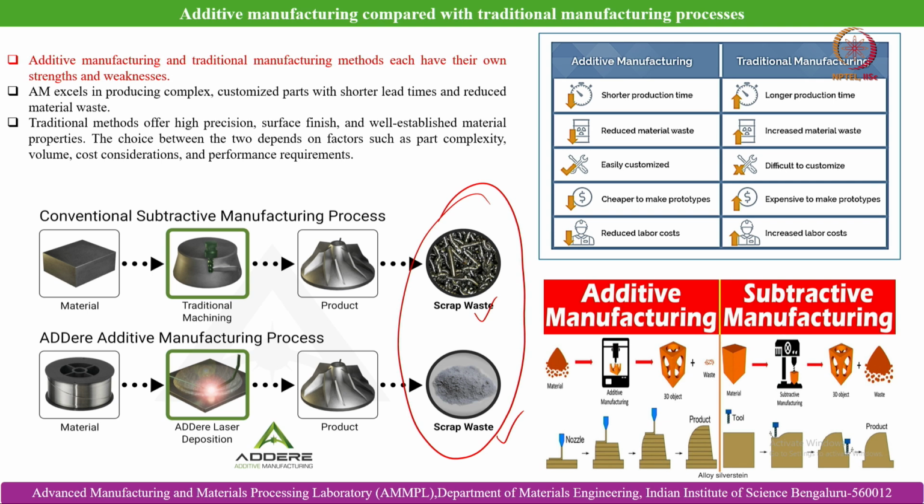So, you can very well understand that it is most viable economically for costly materials, and it can also reduce the efforts involved in tooling, design and manufacturing. So, it is quite useful for precision parts like aerospace, rocket engines, and also for costly materials with minimum batch production. However, the moment we go for mass production with a much lesser or cheaper material, then again cost wise it goes behind the conventional manufacturing processes like casting or metal forming. So, again that trade off needs to be met based on the problem in hand.